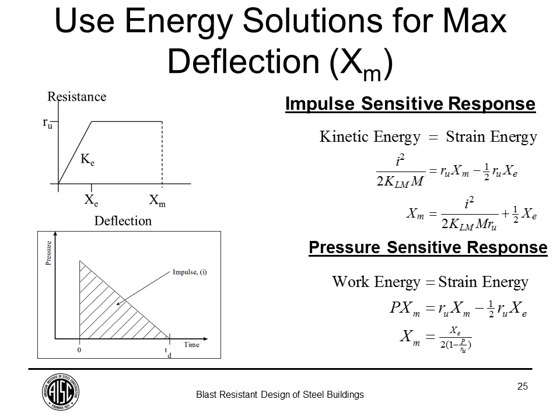So now let's just talk about the energy solutions, which is one of the methods for analyzing the blast response of a component. Again, we have two cases. What we're trying to do with an energy solution is match the energy from the blast load to the strain energy that is stored in the member.